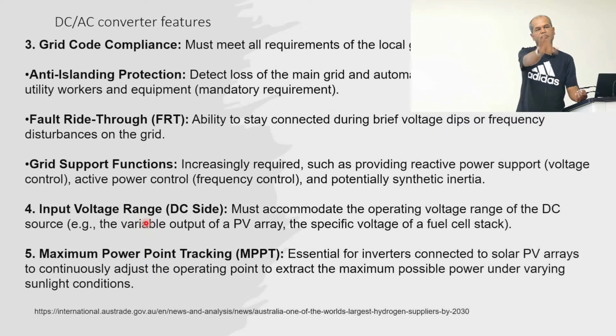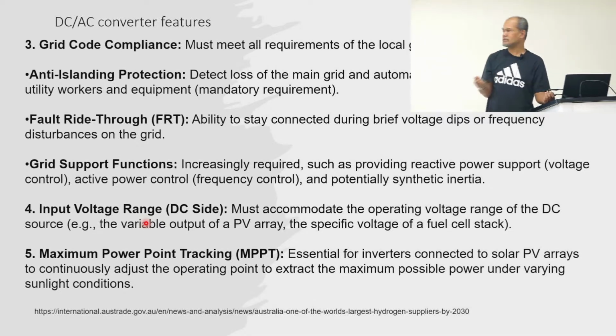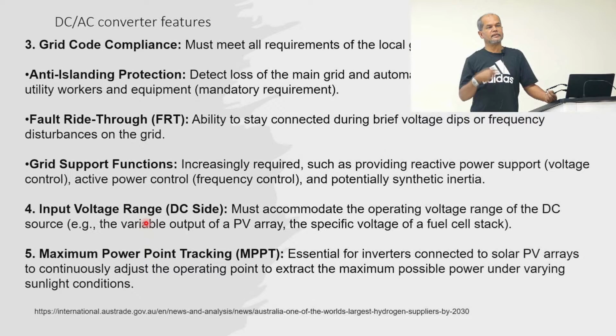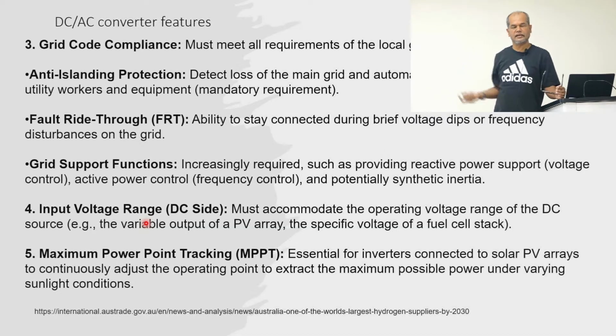If you are private, or you have your own power generator or a small power system, and you want to connect, then you have to show grid compliance. And grid compliance again is mainly voltage, frequency, and sometimes n-1, n-2 requirements. If any device gets disconnected, it should still be able to meet the grid requirement in terms of voltage, frequency, and power quality.